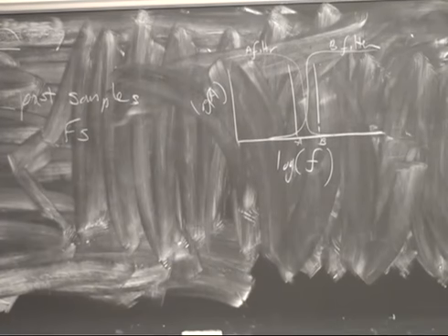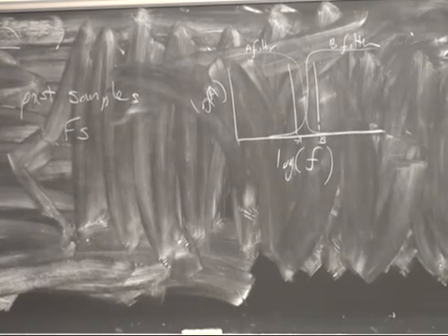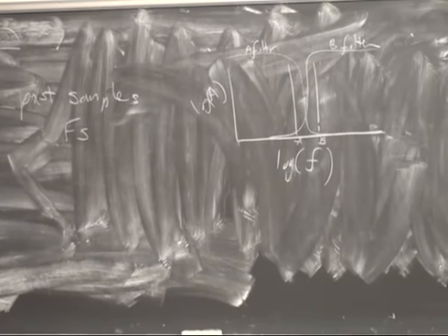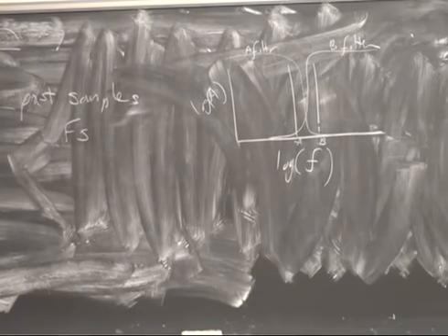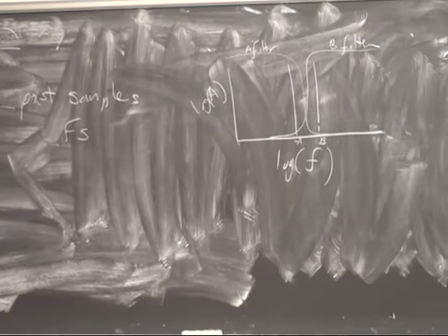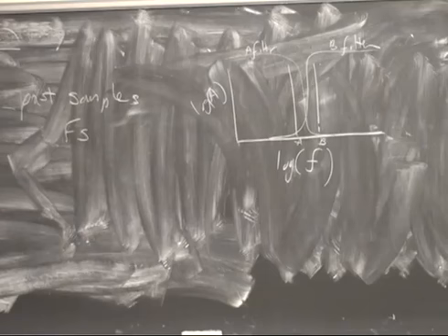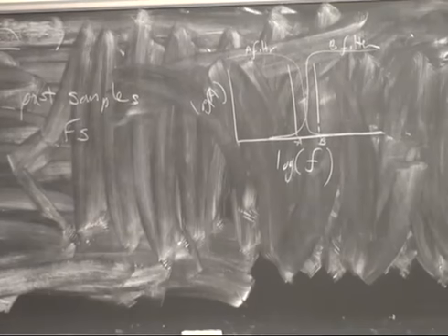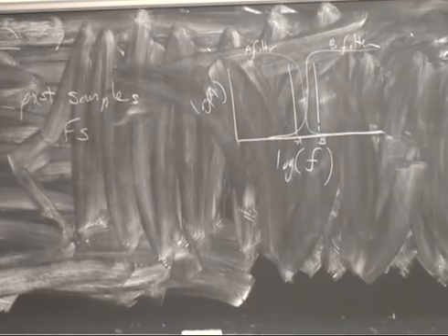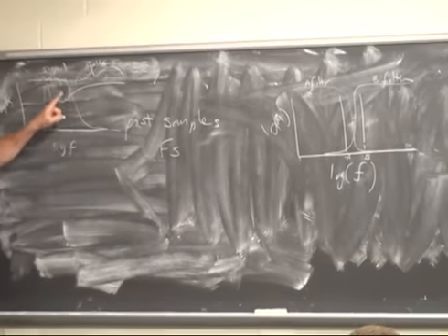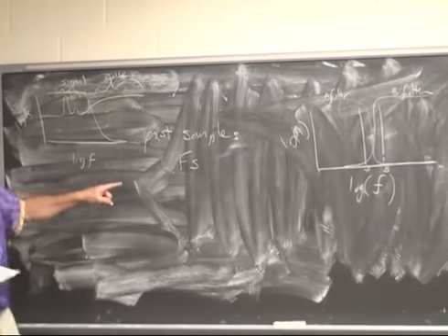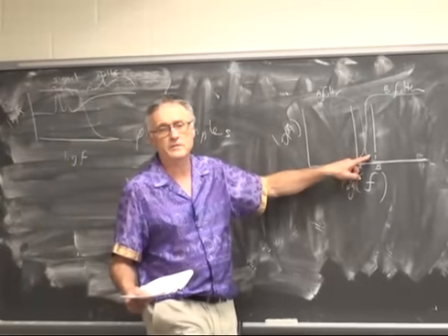So in this case, what you would like to do to separate out the signal from the noise is to have a filter which distorts the signal as little as possible. So the filter has to be quite flat in this region. It has to have a uniform response in the signal region, and then it has to attenuate the noise very well. But the transition speed between those, the rate of cutoff, may not be as important as it is if you're trying to discriminate two sine waves side by side.